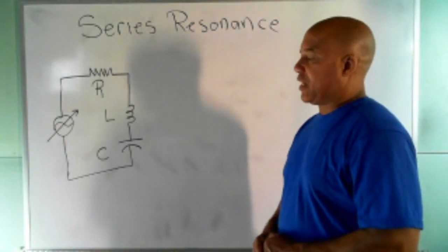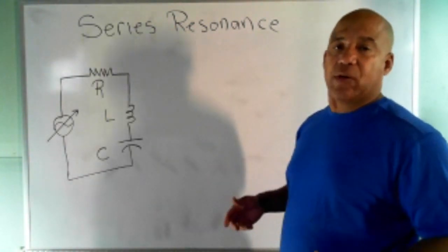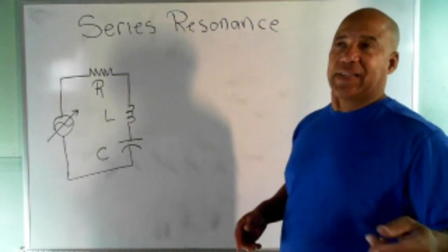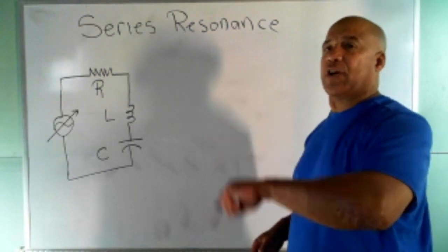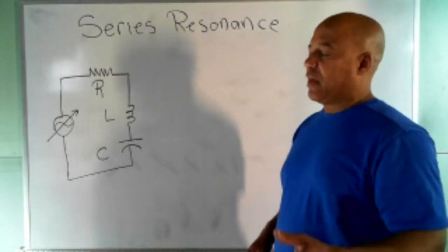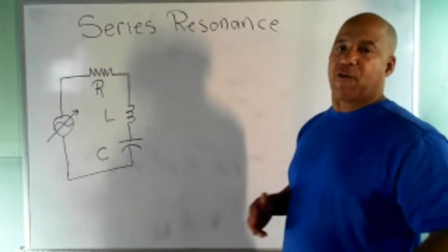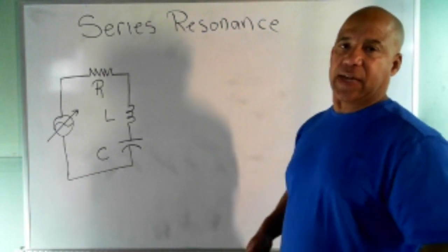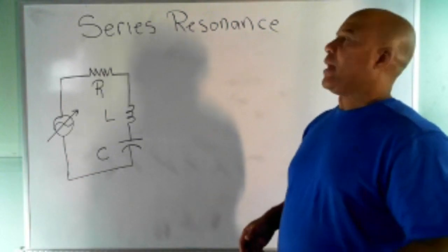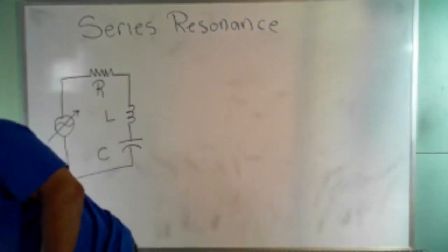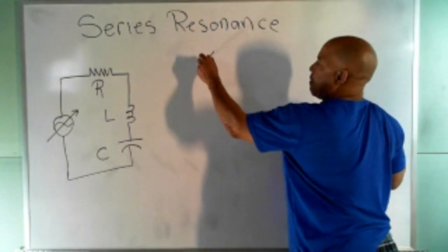Something else we learned is the frequency at which objects resonate or vibrate. I shouldn't say objects, I should say circuits. You can think of that charging and discharging of the capacitor, the discharging of the capacitor and the charging of the inductor and vice versa, going back and forth. Any kind of back and forth movement, you can give a frequency number to it: so many hertz, or so many swings per second, or cycles per second. And what we learned about those electrical oscillations, when we talk about electrical resonance, is that it happens when this is true.